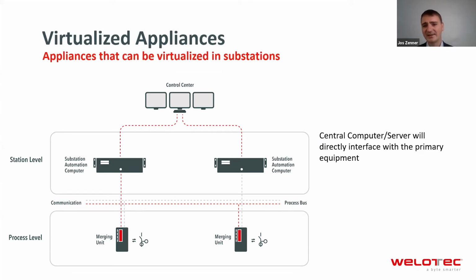The requirement for that is that you have real-time hypervisors. So at the moment we are working on realizing real-time operating systems, real-time hypervisors to also virtualize safety-relevant applications like protection and control. So at the end, you have software-defined protection and control instead of protection and control that is really hardware-based.